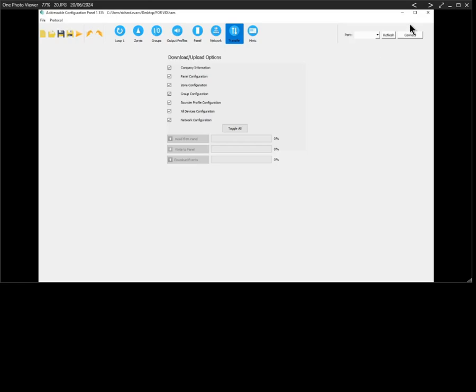If it doesn't connect, hit the refresh button and the panel will then call up an additional or other comms ports to use. Try reconnecting, and hopefully within 1 or 2 pushes, you'll get a connection to your panel as it cycles through the different ports. Normally it takes only 1 or 2 tries.